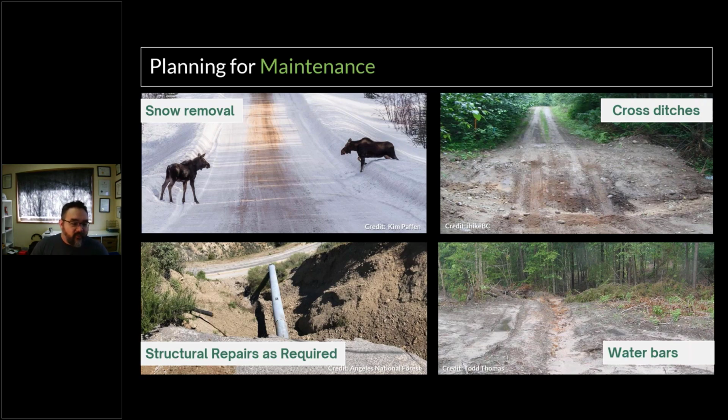So in the springtime, we don't have a corridor of melt. And that goes all the way back down to planning at the initial stages to make sure your right of way is the right width and your fill slopes are the right slope. But you also need to think about things like seasonal deactivation. On the right-hand side there's a cross ditch over a water bar. Now, cross ditches are just what they say. They take ditch water or flows from the ditch side across the road prism, and that can be even just as a fail-safe beside an existing culvert. Or temporary water bars.